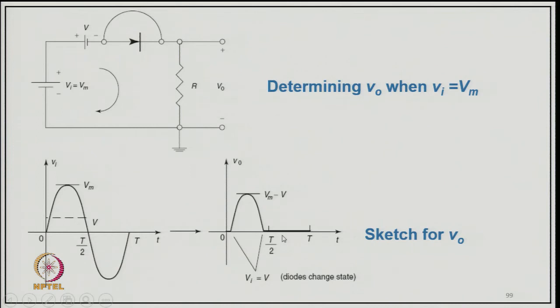And you can see here the diode which is in series. So, it only changes the voltage; typically, starting from here, it will start conducting only at the voltage of V, and only this much portion comes as a clip at the output. So, it starts conducting when the supply voltage is equal to V, and stops conducting when it equals minus V, and so only that much portion is in the output here. So, you are clipping only a portion of the positive half cycle; not the whole positive half cycle is across the resistive load in this circuit. So, that means in this kind of clipping we are providing only a portion of the half cycle, not the full cycle.